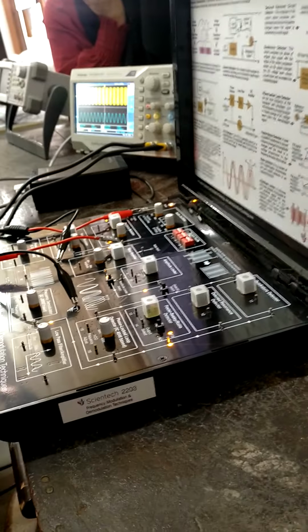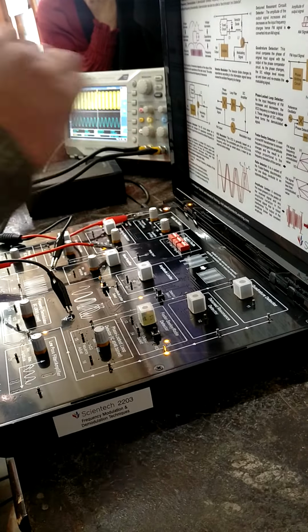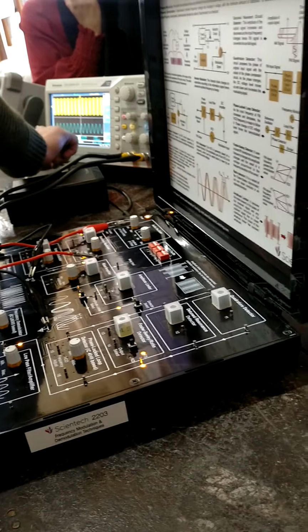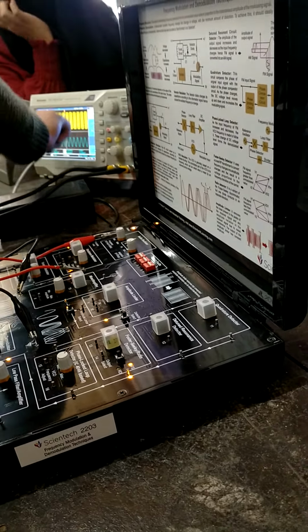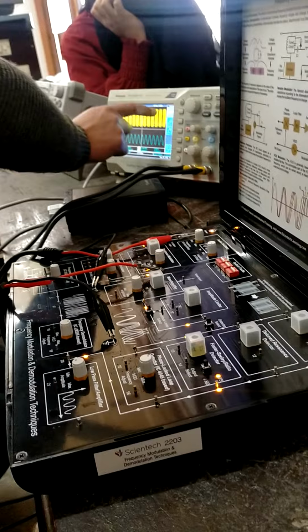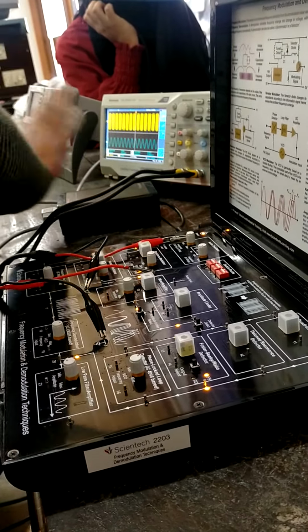Okay. After that, you will observe the output of the reactance modulator. You observe a signal like this. So as you notice, whenever the amplitude of the modulated signal is changing, at the corresponding points there are also compressions and rarefactions. Okay. So this shows that whatever message signal you are giving, its information gets stored in the compressions and the rarefactions of the carrier signal. You know? So this signal represents the FM frequency modulated signal. Okay. So this you have to first of all observe here. Okay. And you have to take the photograph of the same.